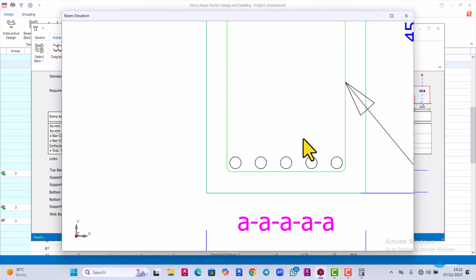So when you pour your concrete, how will it pass? The aggregate will hang on the reinforcement, while the liquid aspect of the concrete will flow. This will cause what we call segregation.